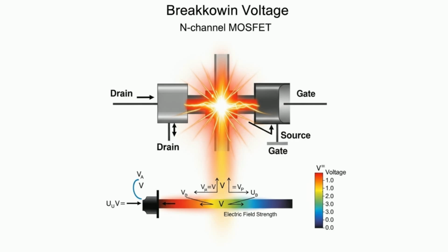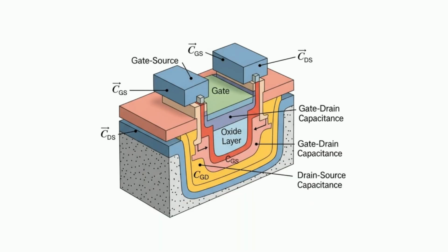devices. At the same time, wide bandgap semiconductors like silicon carbide (SiC) and gallium nitride (GaN) are being used to build MOSFET-like devices for high-power, high-frequency applications. These materials offer faster switching and greater efficiency, especially in electric vehicles, industrial systems, and renewable energy.